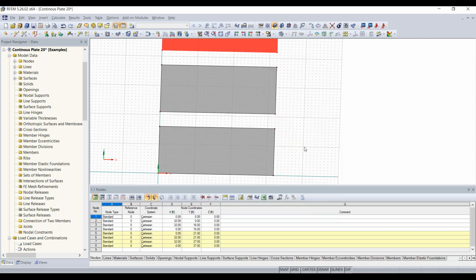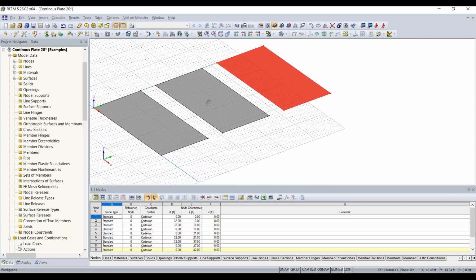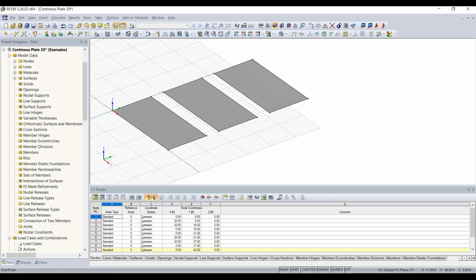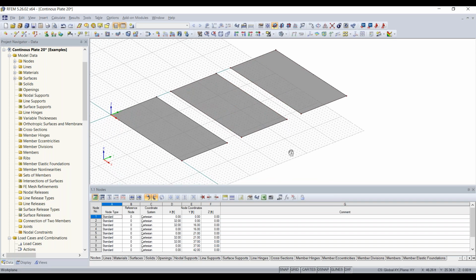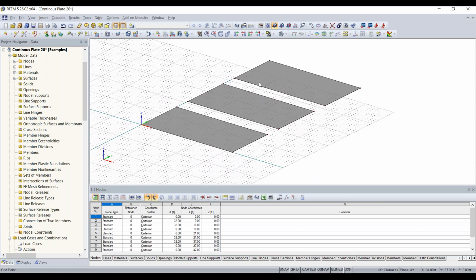And then I'll click OK. And now you can see that I created a second copy of the plate at 21 feet. The reason for that is because I wanted it spaced 5 feet from this plate here. So now you can see we have all three of our plates, and there are a couple of ways of modeling your plates or modeling a copy of something.